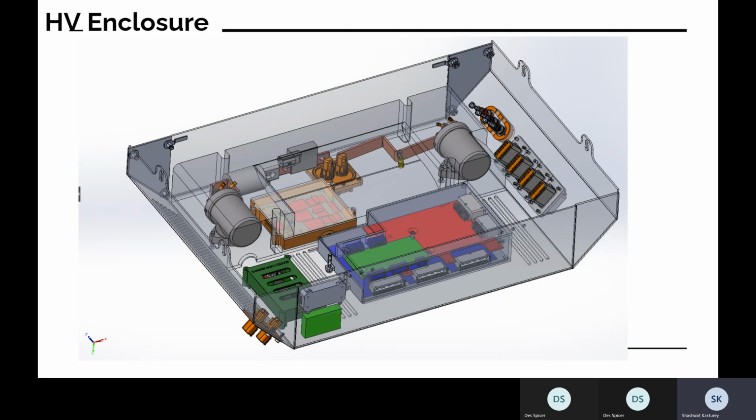The voltage you register is really low when you're only pulling from 5 cells in parallel versus 6. So if the AMS sees that a string of cells is pulling really low, it's almost sure that a fuse is blown. That's how that is managed when a fuse blows.